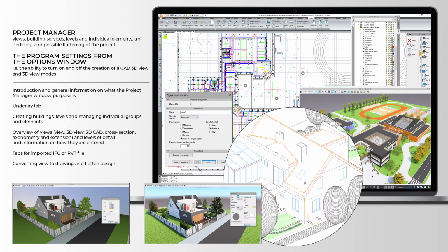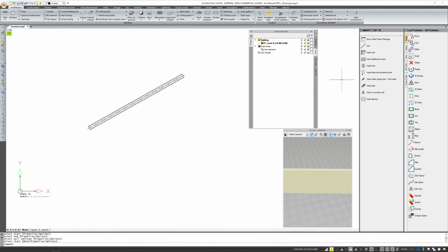Okay, I just had to turn it on here in my computer. So let me just find out if you mean from the left side, Arthur, because adding a section is from the top right-hand side of the mouse here. So if I'm clicking it here, right, you have insert view, insert 3D CAD view, and insert cross-section. I am not from the left. On the left, you only get the underlays here visible from RVT and IFC. Maybe if you can expand your question a little bit more.